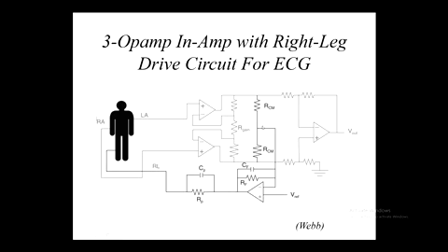That now is being inverted and a little bit of capacitance put in. It's got an integration function here and some resistance to protect the subject, but we've got the common mode signal being put back into the right leg. So next time it comes around along with right arm and left arm signal, it's been subtracted away from itself, if you will. So we've reduced common mode signal by stuffing it back into the patient's leg.